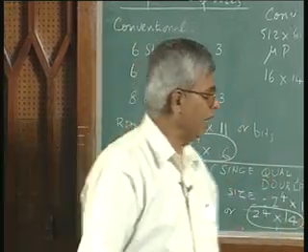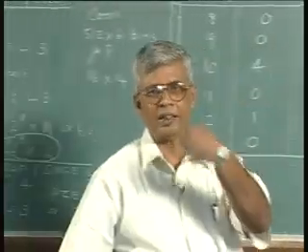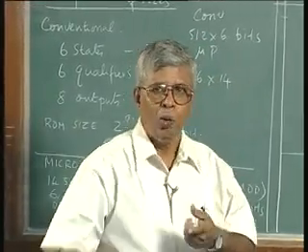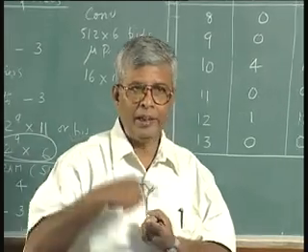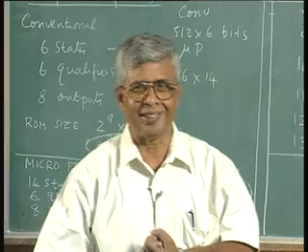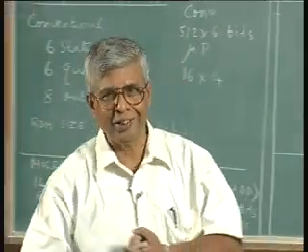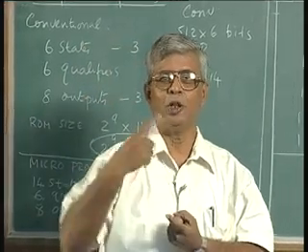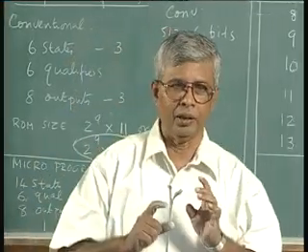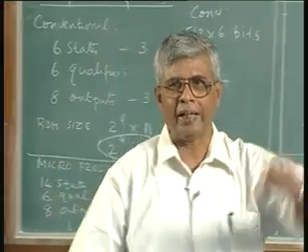One minor modification at the end, and that would be to make it into a single qualifier, single address design. The only requirement being one of the addresses should be an increment of the present address, other address can be anything, and that is also called a jump address, even though we call it true address or false address, because either you increment it by 1 or jump to a new location. So, some people call it jump address and some books call it jump address, anyway it does not matter. So, we need to give only one address called the jump address, which is a non-incremental value of the address.